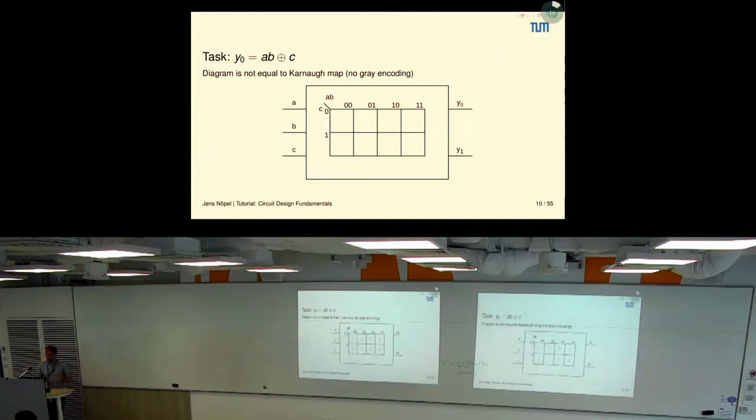And a very simple approach most of the time is to first draw a logic table that realizes the functionality, and then you can think about what might be a good idea, and then you come to the result and store the logic table inside the lookup table and realize its functionality.